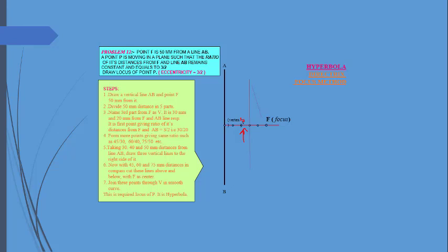Now take a focus at 45 millimeter. The vertex is taken by drawing a line from the focus that is 45 millimeter and 30 millimeter above. As I have told you, the ratio for a point lying between focus and vertex will be the same wherever the location of the point is. So here you will see the points where the lines intersect each other. These are the different points that we have achieved from the intersection of these lines.